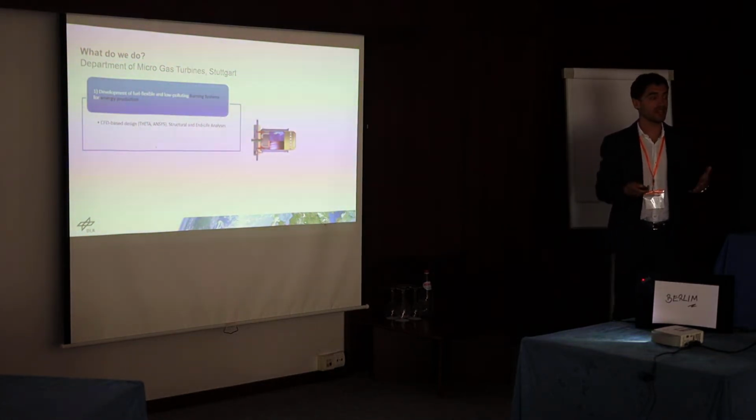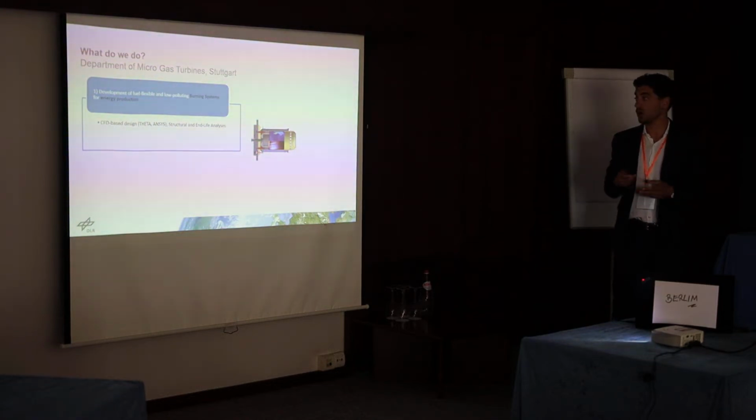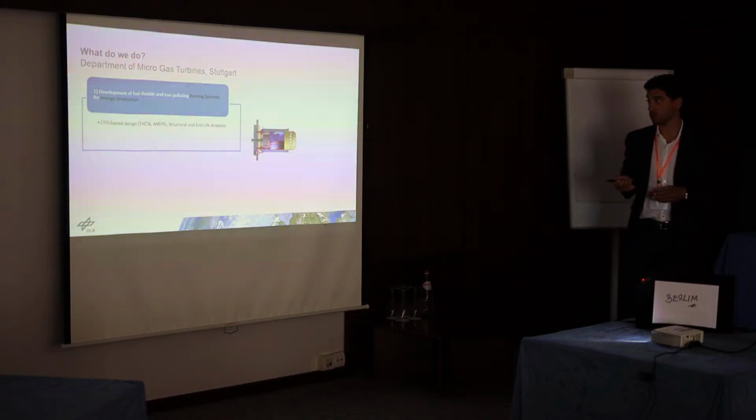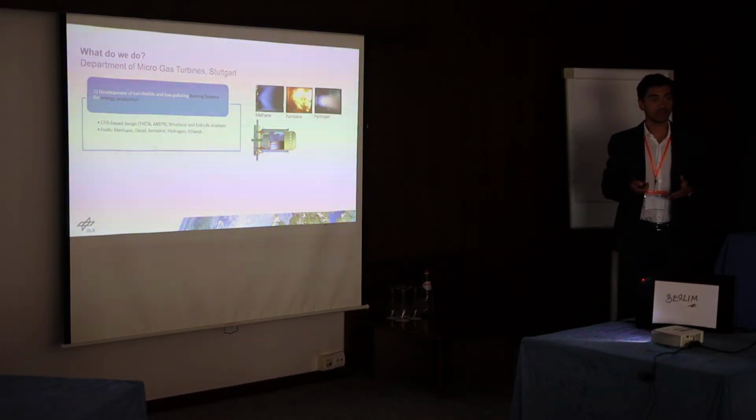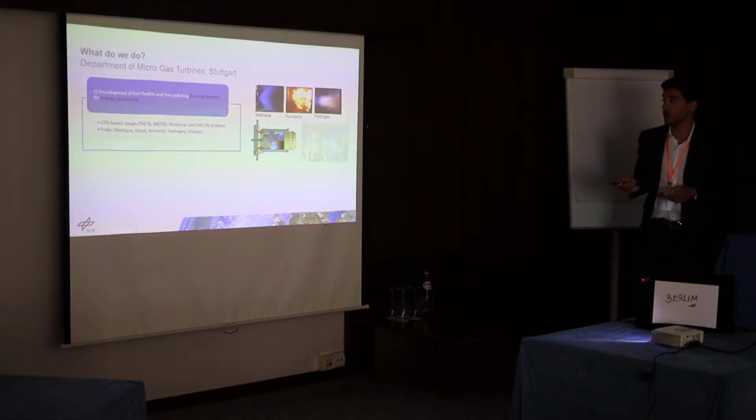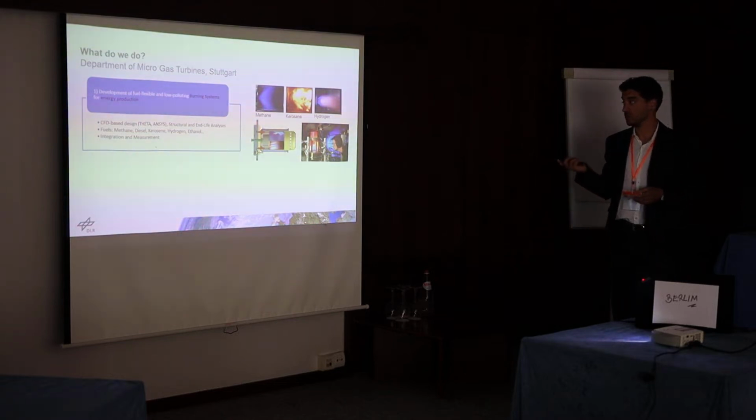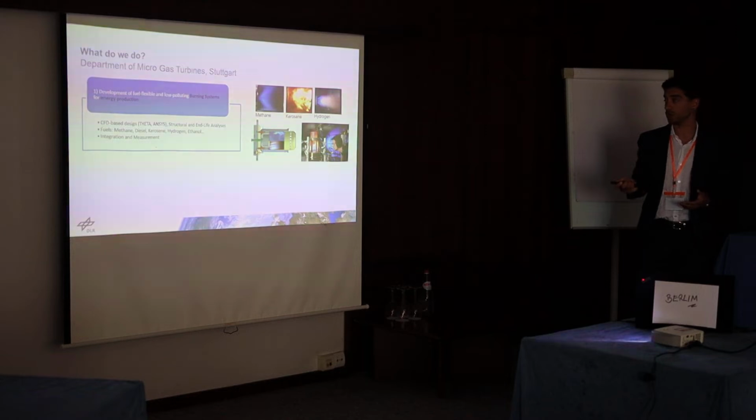So we design and develop new combustion chambers for micro gas turbines, and we perform structural and life analysis. So this is a representation of one of those components. And we simulate and test very different fuels, for example, classic methane, kerosene, so we also apply droplet combustion, and now also hydrogen is a very hot topic. And we instrument and measure in our labs the flames, and we measure the pollutants and so on.